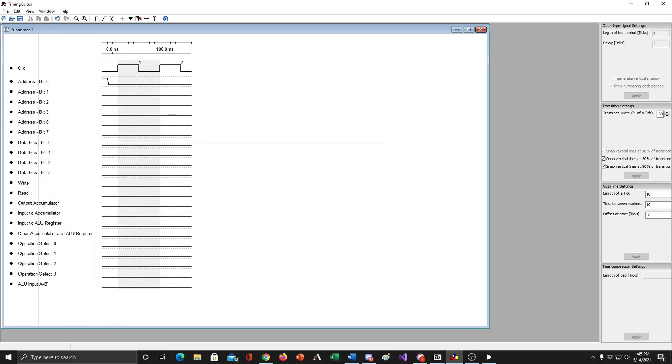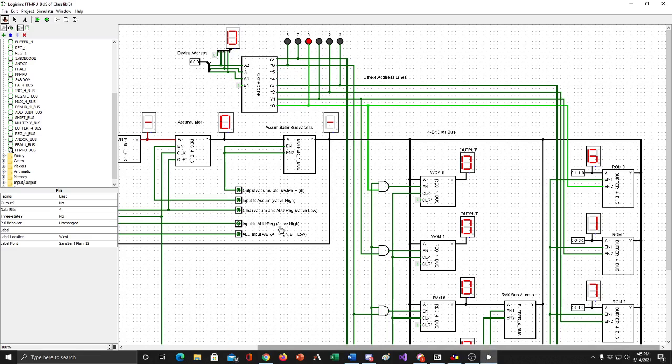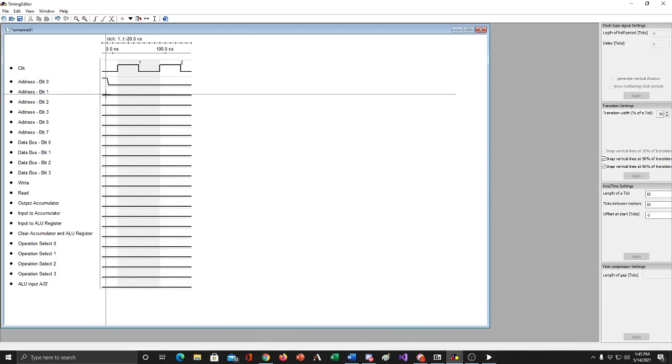So the address bit is high, and then we also need to check on the data bus. At the moment, the data bus doesn't have anything on it. And if we go peek at that, that's confirmed. When you are drawing it by hand, you can kind of scribble through it a little bit. At the moment, there is nothing on the bus. So for my purposes, I'm just going to go to the data bus and put this gray on it to indicate that there's nothing on it. It's in high Z mode, but you can indicate that however you want.